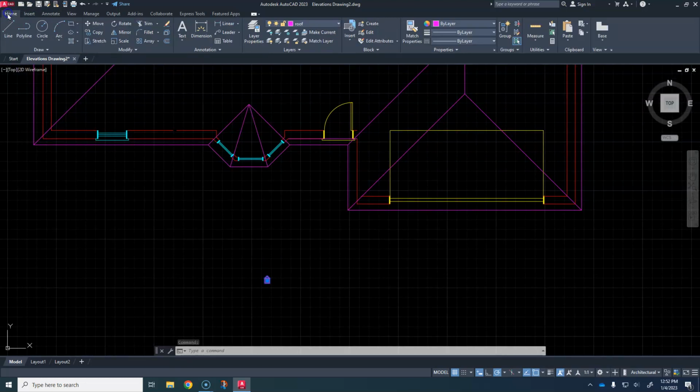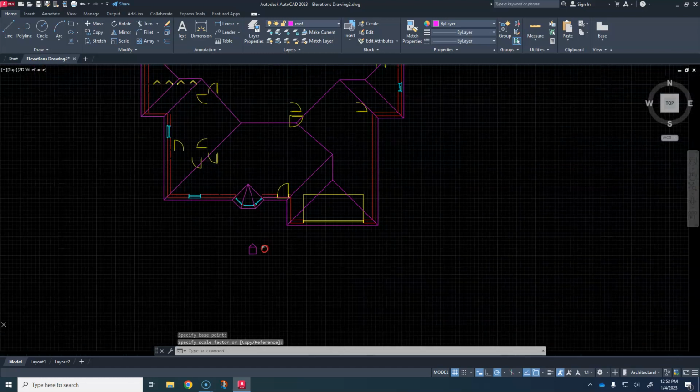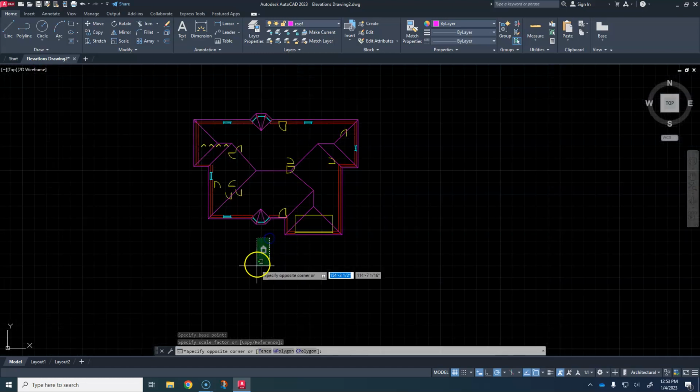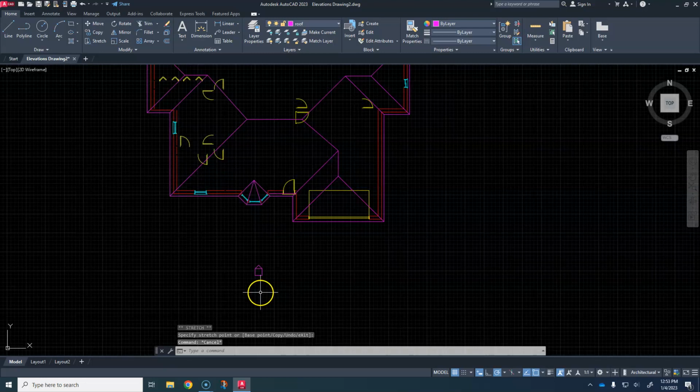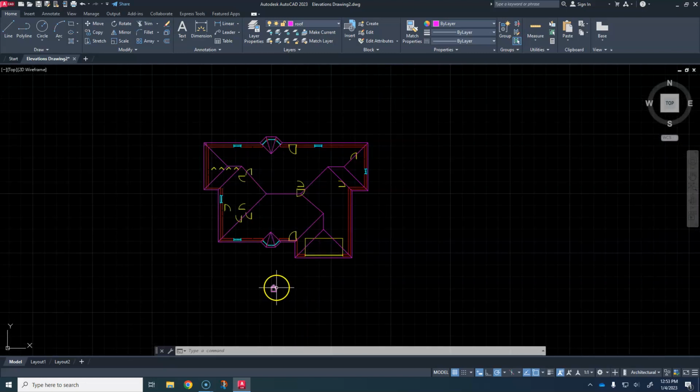When you draw yours, just draw it to the size that I drew it to, to keep from having any confusion. I'm just going to enlarge this one for the sake of the video. Okay, so that's easier to see. It's placed right outside the dimension lines, and it's pointing towards the front of the house, saying, hey, there is a drawing that represents the front of the house.